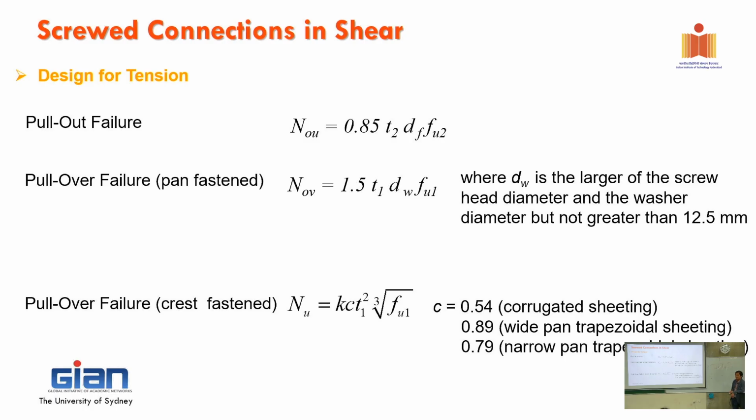Yes, so interesting on that one. But at the moment, in this equation, we don't have that come into play. It's all about the dimension. So I think they presume that it's clamped somehow and pulled up. And you have to pay attention a little bit here. The thread of the screw is normally very small for the self tapping. But with the self drilling screw, we have a deeper thread.